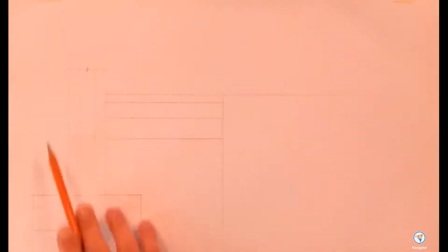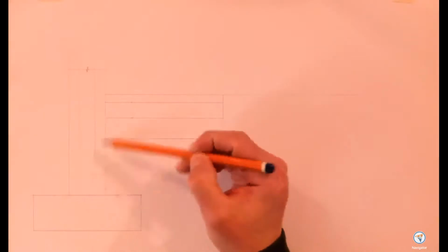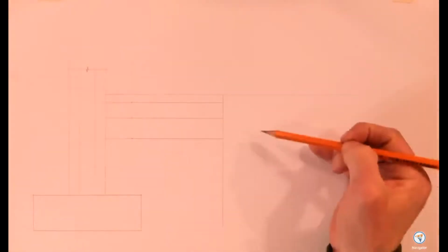These are all construction lines. Don't draw these heavy, because we're going to have to do some changing here. We're going to have to put in vents and stuff like that in a while. So that is our solid concrete ground floor. We'll get on to the suspended timber floor part then.